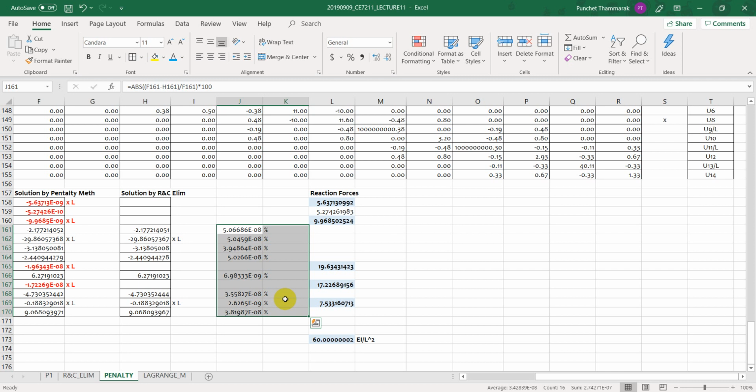But for finite element analysis, especially when you have different element size, like some area you put a very fine mesh, small element. So for very small element, your stiffness will be extremely high. If you discretize your bar member into small size, the EA over L that controls your stiffness, EA will be the same, right?